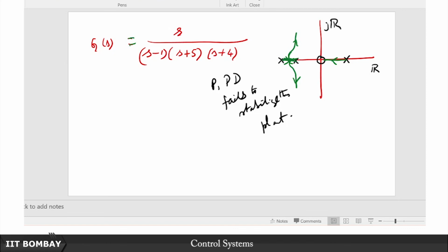Now what we shall see using the state space method is that, subject to certain restrictions and conditions, which will exactly boil down to joint controllability and observability, I can place the poles anywhere I like. In fact, if I just have controllability and access to the states, we will discuss more of this in the next lecture, I can place my poles anywhere in this complex plane that I like. I have no restrictions on where I can place the poles. This is one of the greatest triumphs of these modern control theoretic approaches.